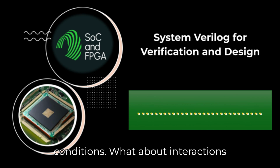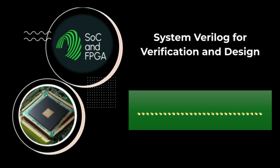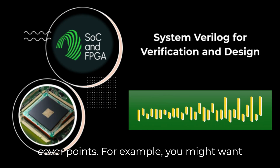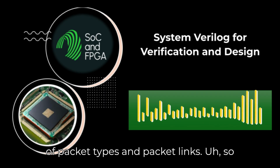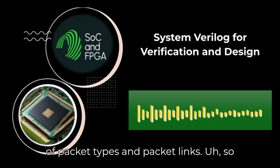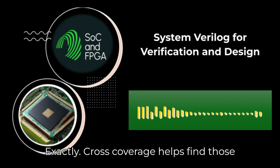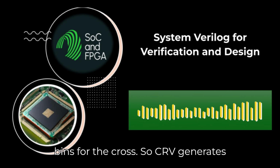What about interactions between different things? That's where cross-coverage comes in. It's crucial. You use the cross keyword to define coverage measurement across multiple coverpoints. For example, you might want to ensure you've tested all combinations of packet types and packet lengths. So making sure feature A works correctly under all conditions of feature B. Exactly. Cross-coverage helps find those tricky interaction bugs. You can use operators like binsof to select specific bins for the cross.